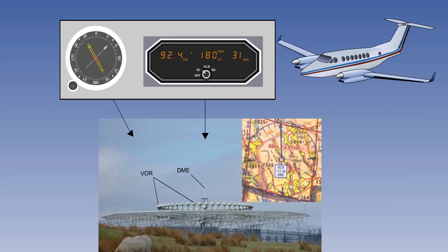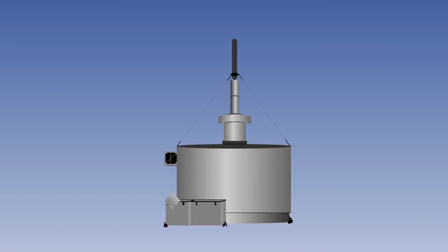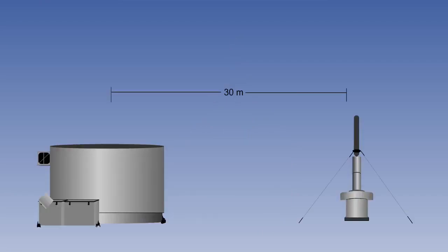To facilitate and speed up frequency selection and to reduce the pilot's workload, VORs may be frequency paired with a DME or TACAN installation. So, when the VOR frequency is selected, the DME is also selected. Ideally, both sets of equipment should be located in the same place, but this is not always possible. The term associated is used to denote that the equipment is either co-located or close enough to make no significant difference. For a terminal VOR, this is defined as a maximum of 30 meters.